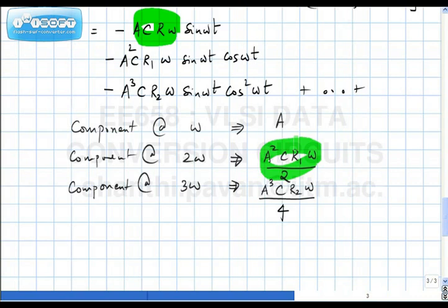The second harmonic is coming from the square, alright? And what is squaring? It is taking the signal and multiplying it with itself. So any component at 2 omega will result from the input somehow getting multiplied with itself. And when the input has got an amplitude A, when you multiply it with itself, the strength of that component has to be proportional to A square, which is intuitively why the second harmonic always depends on A square.